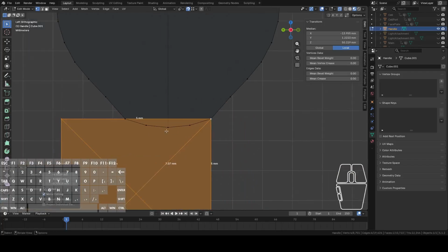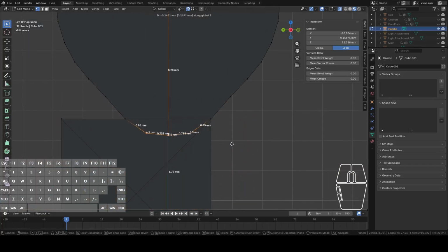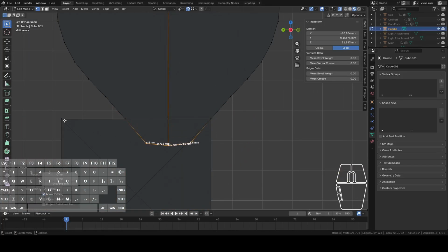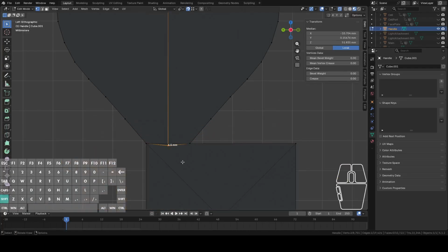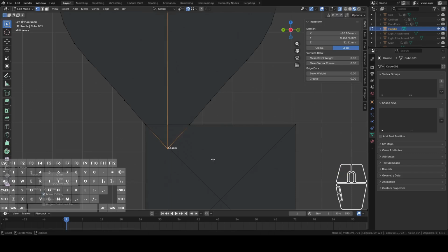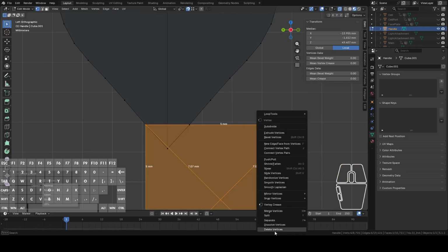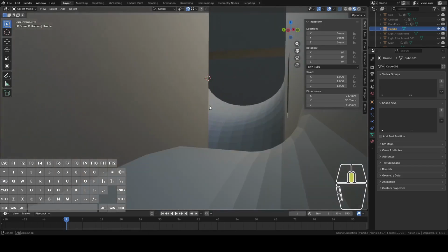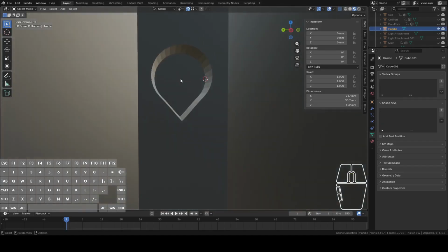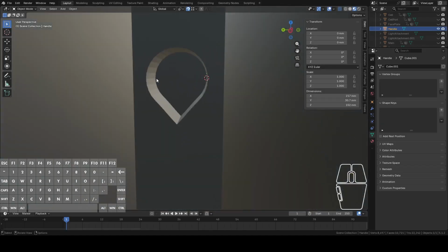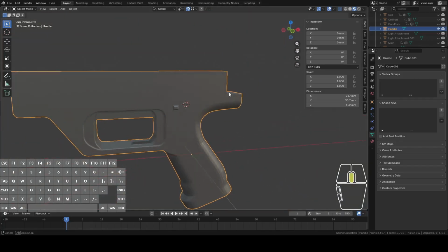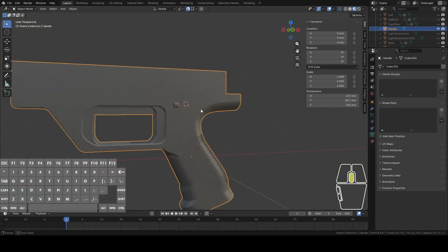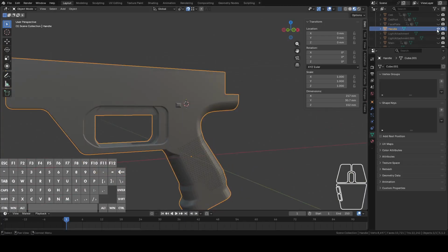Snap it here, these also, all of them will have to be. Make sure it's over. And then this one, the last one. And now we have that teardrop shape, so it shouldn't feel the need to print any support in there because most printers can do at least a 45-degree angle of overhang, and digging that support out will be a hassle, so that should be fine now.